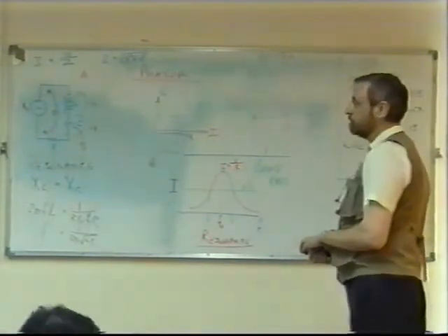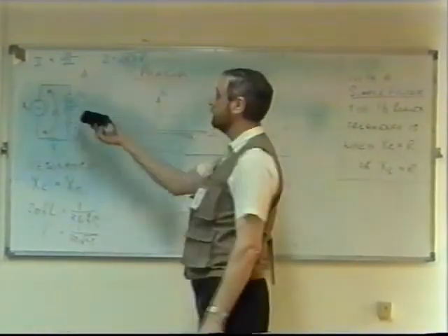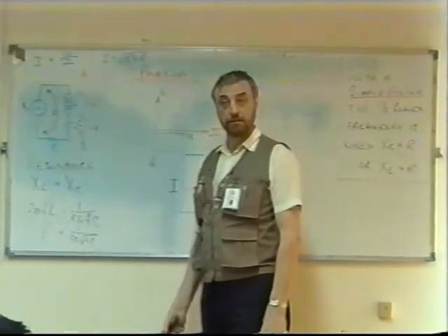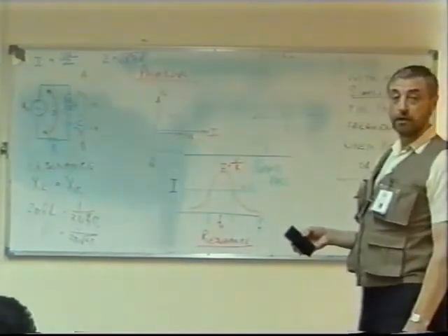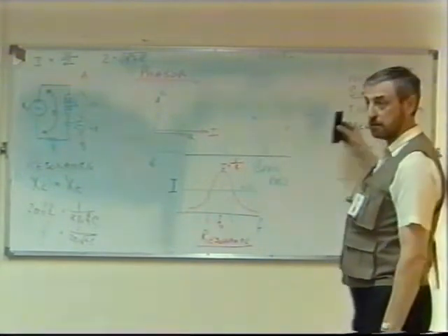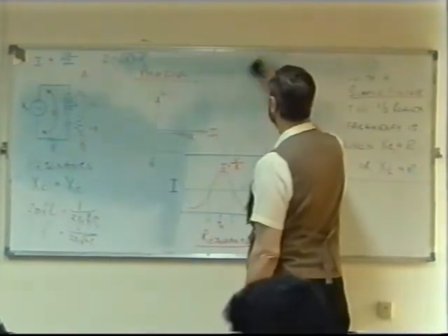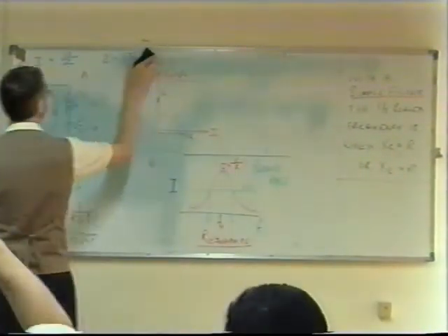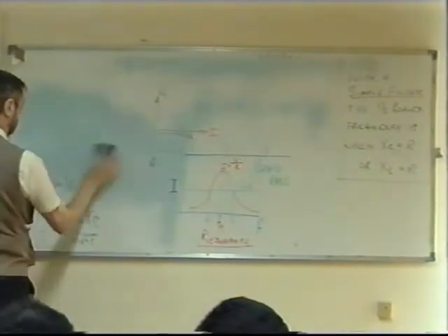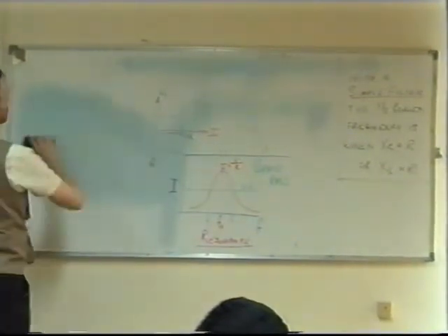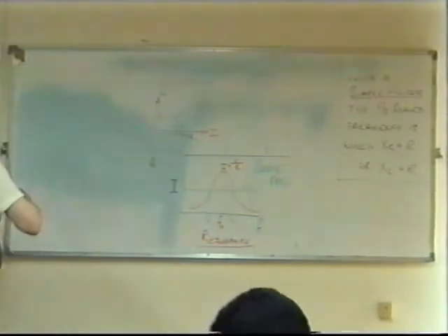And again, there are different designs of tuned circuit. Here you can see clearly that we've connected our inductor and capacitor in series. But it is actually possible to design a tuned circuit where you have your inductor and capacitor in parallel, not in series. So let's have a quick look at that first. The mathematics involved is just the same, not a lot of difference, but let's draw the circuit.